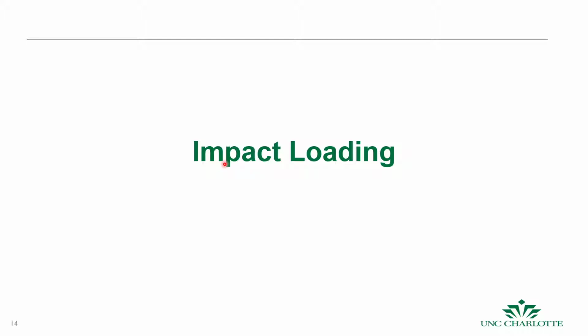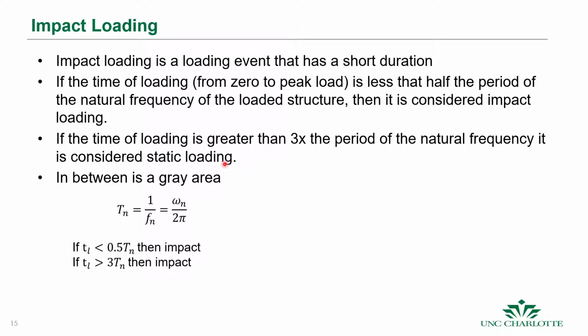So we'll give an example of some basic frequency analysis a little bit later, but now we're going to talk about impact loading. Impact loading is a loading event that has a short duration, as opposed to static loading where we'll load it up and then that load stays there forever. If the time of the loading from zero load to peak load is less than half the period of the natural frequency of the loaded structure, then it's considered impact loading.